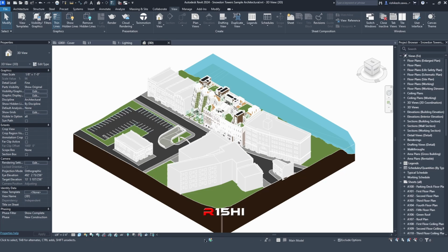You also have different settings over here for the status bar again. One is that you can create work sets. Work sets are defined to work on the project on a collaborative basis using different users. You can assign a different work set for every user, and then they can access the file using that work set name. The owner of the created element is displayed over here, and without the permission of that owner, it is not possible for other users to edit the element created by him, unless he grants access to them or he relinquishes all of his ownership of the created elements.